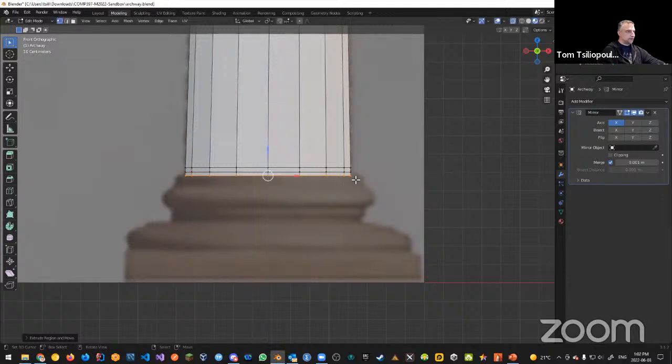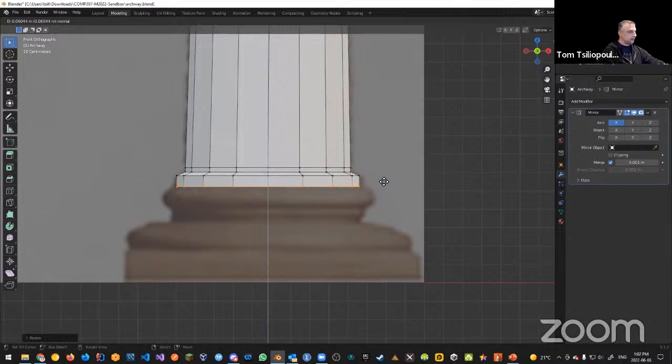And if I was to do this and then just scale out the bottom, so scale this out, you can see we get a bit of that shape that we want, to some degree. And I want to do the same thing. So all I'm doing is extruding and scaling. So the E key and then the S key, the E key and then the S key over and over again. Watch. So I'm going to do the E key where I extrude down, right? And then I want to do the S key.